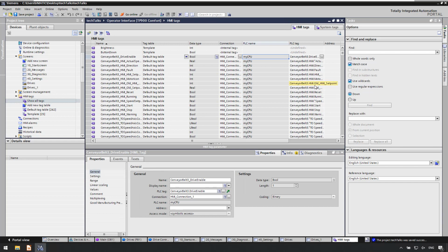Another thing could, for example, be a service tool. That is a little exe file that a service engineer could run to automatically extract the project from the machine, save it on the desktop, and generate a list of differences between the project running on the machine and the one that the machine was loaded with. All this without even showing the service guy the TIA screen at all. It could all do this headless, and then they can take further actions when they have the list. They can see, okay, these things changed, Mr. End Customer, what have you done? This is why it's not working.